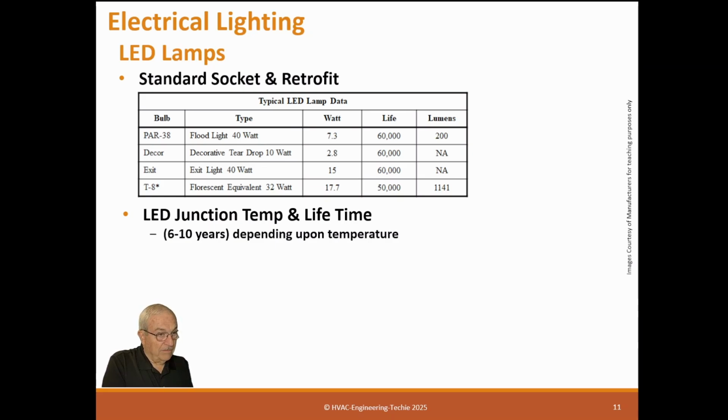Well, for an LED, they put a whole bunch of power to it, where a regular circuit gets just a little bit of power. Because they're trying to produce light, they put a whole bunch of power to it, and that causes temperature where those two things meet. And the higher the temperature, the less the lifetime of the bulb. That's why, up till now, most LEDs didn't last anywhere near their projected lifetime. The reason is that in the real world, that junction temperature was much different than it was in the lab, or what they intended. So I've had LED bulbs burn out in 6 months, 5 months, 8 months, when they should have lasted 5 years. But they didn't, because the different components in it and the LED itself didn't last.